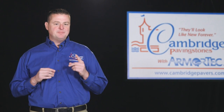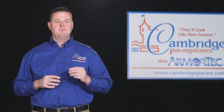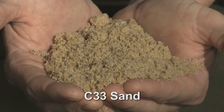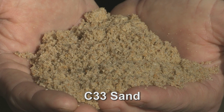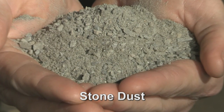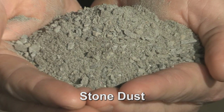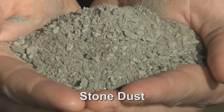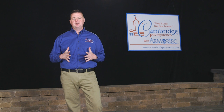Finally, and perhaps most important, has to do with the characteristics of these two different materials. C33 sand should have symmetrical particles, generally sharp, washed, with no foreign material. Waste screenings or stone dust should not be used, as they often do not compact uniformly and can inhibit lateral drainage of moisture in the bedding layer. Stone dust does not provide the lockup that is achieved with C33 sand as the setting course.